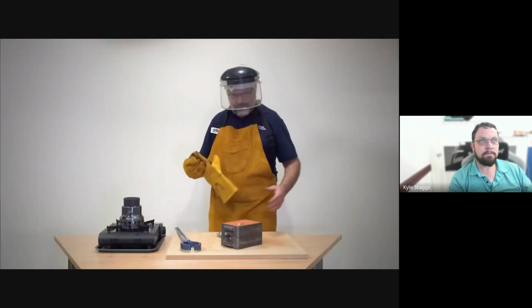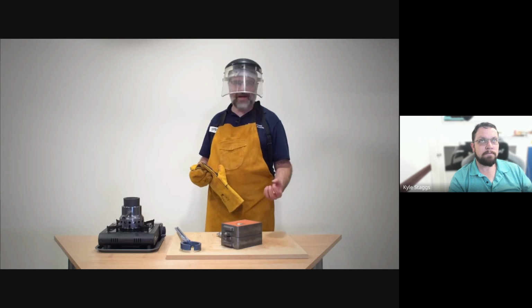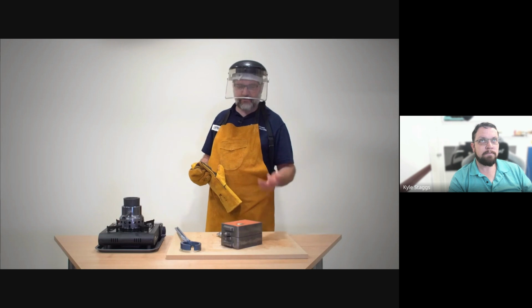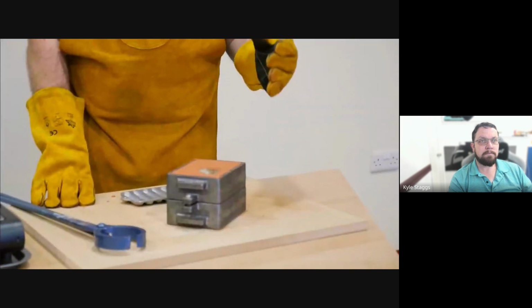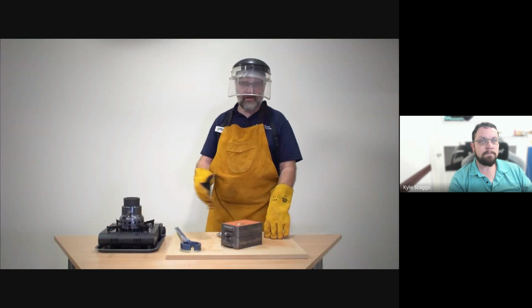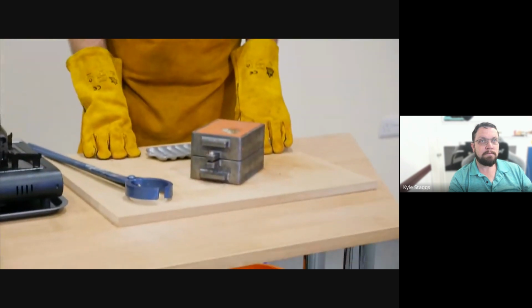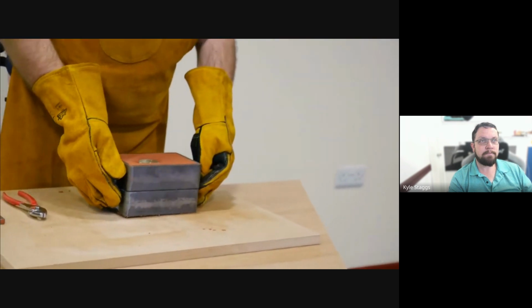The top of the metal is slightly convex when you first pour it, but as things cool down, the casting contracts, the metal will feed in, and we'll see that it becomes concave and dips in the middle of the runner. It may be that you need to provide surplus metal within the mould so that it will keep feeding. You might have to add maybe up to 50% more metal to the mould than you're going to use in your final casting.